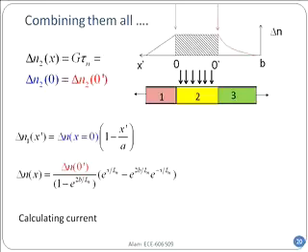By the way, where are those electrons going? They are recombining with the holes, and the holes are being pumped through the contact. So in fact, in the green region, holes will flow in to support the recombination of the electrons. As every electron is moving in, holes will flow in, and therefore the current will flow. Because in the circuit, whatever electron gets out from one side, that must be balanced by the whole current from the other side. Okay, now do you see how to calculate delta n? Delta n is already known at x equals 0 and x equals 0 prime. That is the interface between the magenta and the yellow and the green, right?